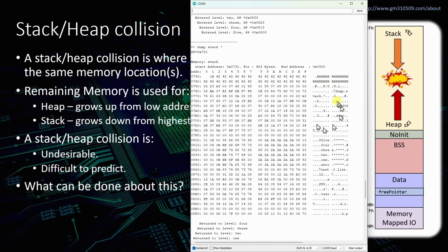So you always want to make sure you have sufficient overhead in memory to allow for this, which is one of the reasons why the compiler will give you a warning if you use more than, I think, 90% or 80% of the BSS and data, that there's not much space left over for the stack. That's why it's giving you that warning, because it doesn't know how much is always going to be used, because that can be variable and random depending on what's going on. And so it wants to make sure there's some free space available for the stack.